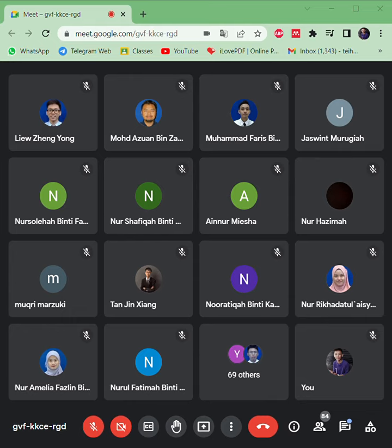So 8 minus 2 is 6. So brick wall area is 6, A brick wall, and U value of brick: 6 times 0.95 plus area of windows and U value of windows 2.8. And when we solve this, we get 1.413, the average.